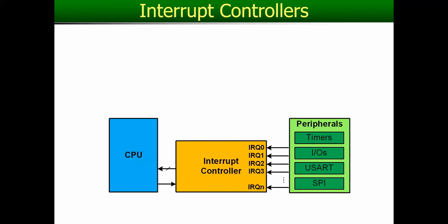It's not like, okay, wait, I'm turning this motor, let it rotate by 30 degrees and then I'll restart. No, you have to leave whatever you're doing, you just restart. Because the reset interrupt has occurred and the interrupt controller will notify the CPU immediately that an interrupt of a high priority has arrived and you need to reset. You have to leave whatever you're doing. Okay, so on this slide, I explained different types of interrupts and the role of the interrupt controller.